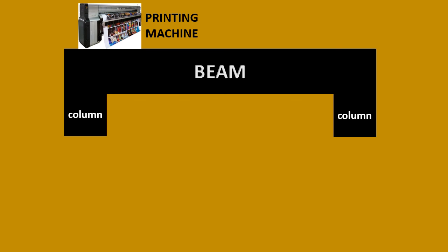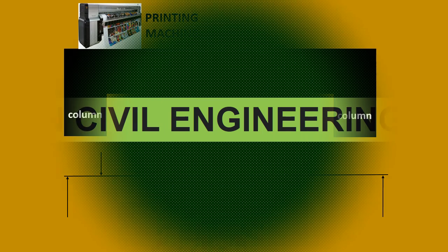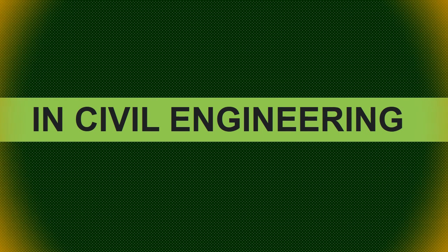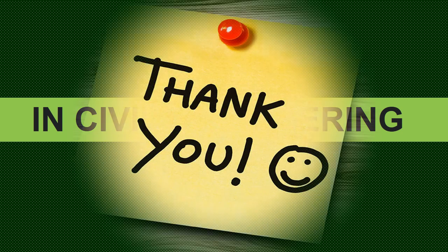Concentrated force. A concentrated force represents the effect of a loading, which is assumed to act at a point on a body. We can represent a load by a concentrated force provided the area over which the load is applied is very small compared to the overall size of the body. In civil engineering, we study only bodies that are considered to be deformed under elastic limit or condition. The behavior of solid objects subject to stresses and strains.